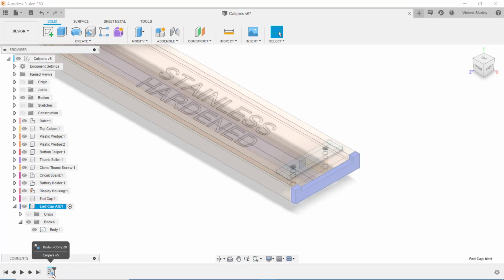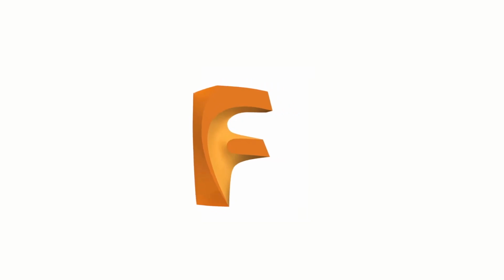This is why it's considered best practice to create a new component first, name it, activate it, and then start designing. Now you know how to organize your design using components and bodies in Fusion 360. Thanks for watching.